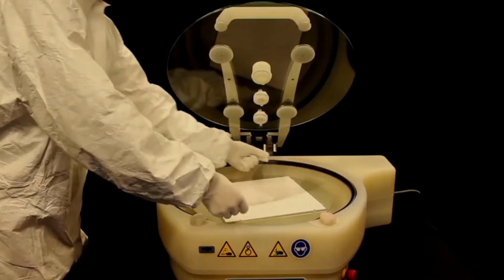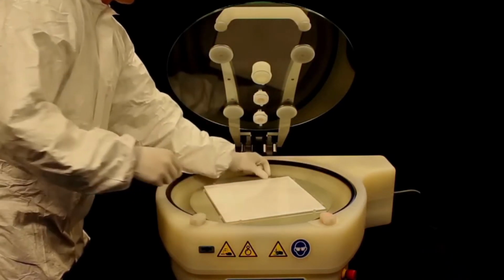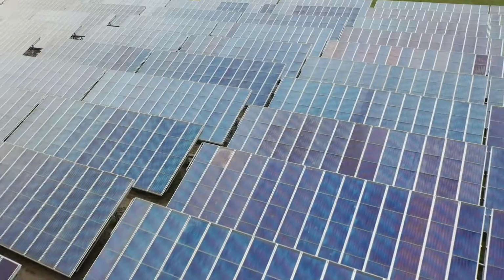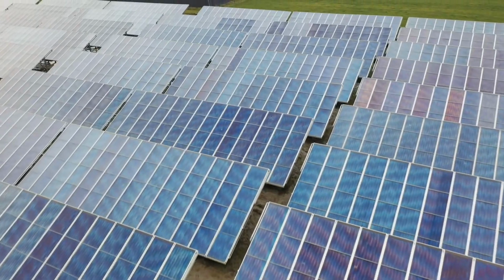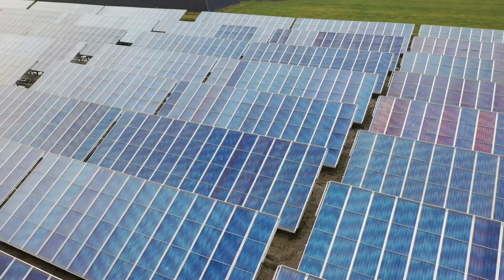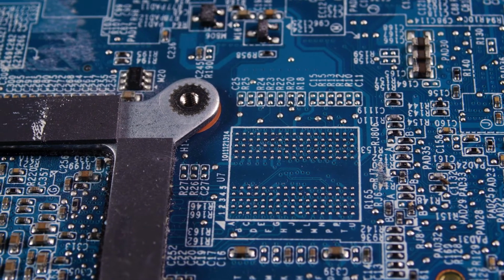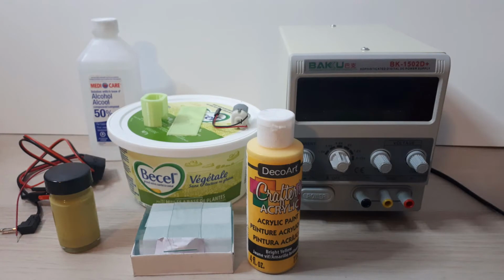Due to its simplicity and reliability, spin coating is implemented in a wide array of engineering applications, including microfabrication of functional oxide layers, photolithography, and the fabrication of planar photonic structures, all of which have use in energy and information technologies. For this demo, we will need acrylic paint or nail polish, 50% rubbing alcohol, small mixing containers, wires, preferably with alligator clips, a hobby motor.